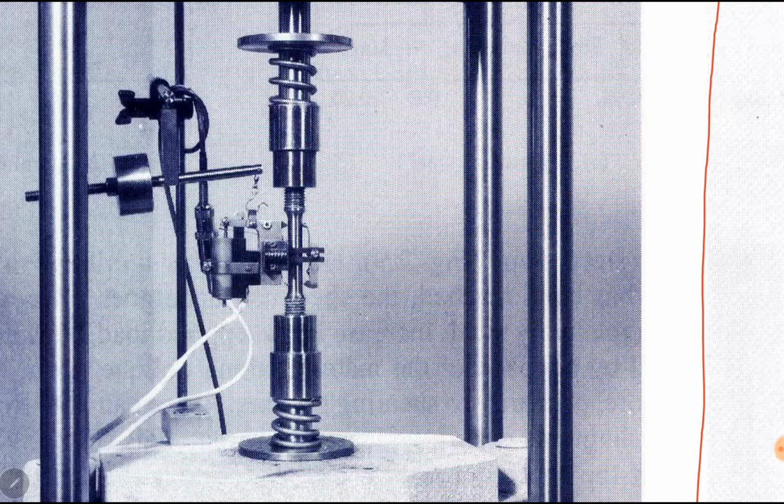So there is a difference between fracture and failure. Failure is not necessarily a fracture. It can be a permanent deformation, or it can be a temporary deformation in the material shape. And the final failure is fracture, definitely. Okay, if we think that we do not exceed load beyond the yield strength of a material, we think that the material will not fail.